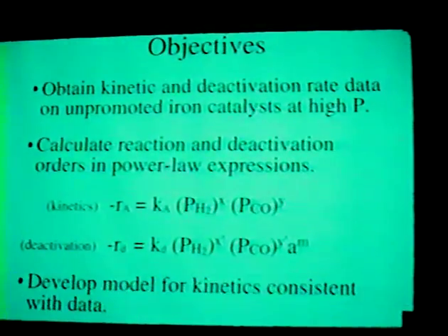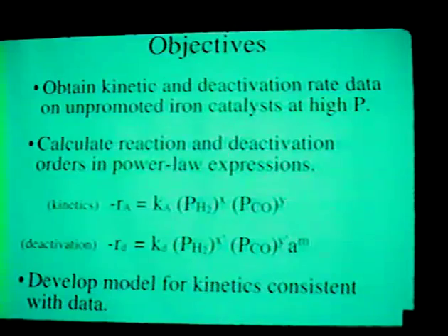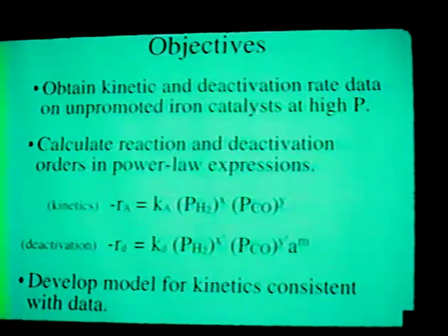At our catalysis laboratory at BYU, we've been studying Fischer-Tropsch on iron, and today I'd like to give some information about the kinetics of the deactivation by carbon on those catalysts. The objectives of this work were to obtain kinetic and deactivation rate data as functions of temperature and reactant concentrations on unpromoted iron catalysts at high pressure. In this work, high pressure refers to 10 atmospheres.